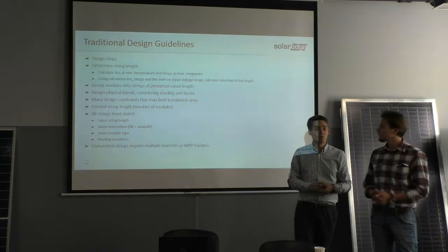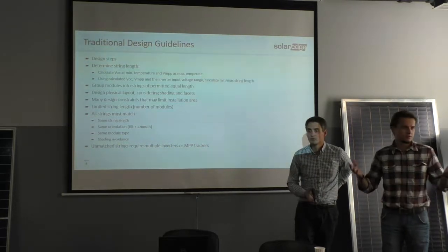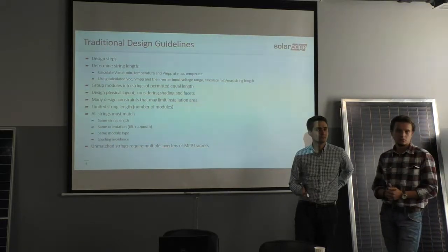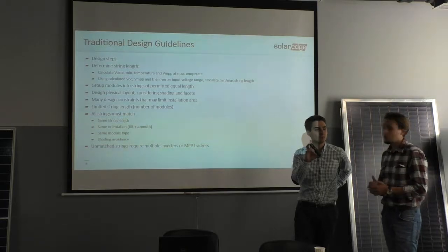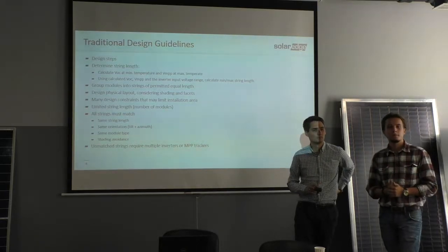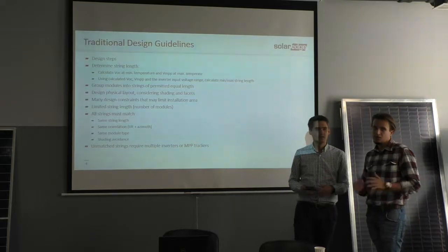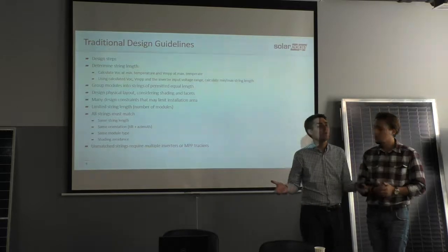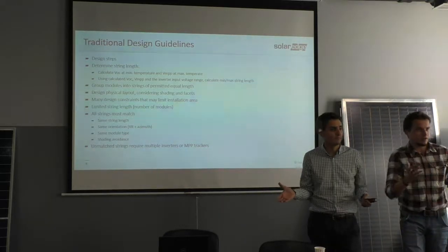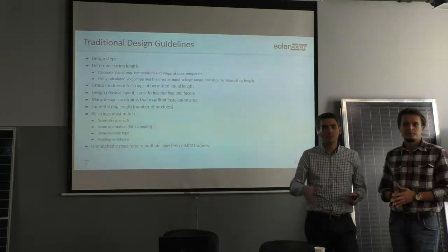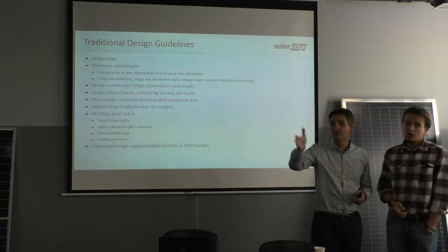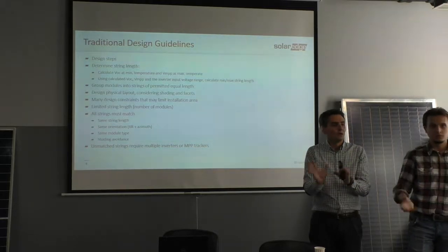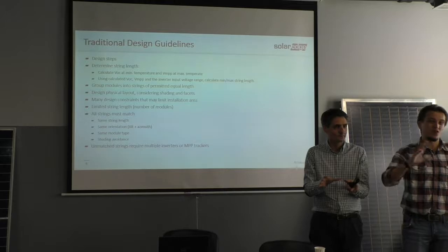And what is the minimum number of modules for three-phase inverters? I mean for a standard inverter. Not 20, minimum. There is a start-up voltage, 200, 300, 350. So around 6 modules, 8-10. Obviously, it depends on the kind of modules and inverters that we have. It's more or less 6-8 modules, plus or minus.